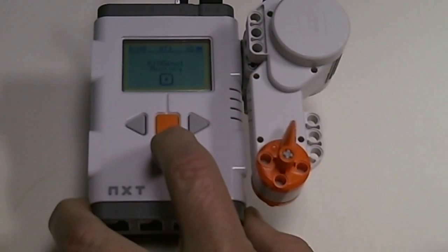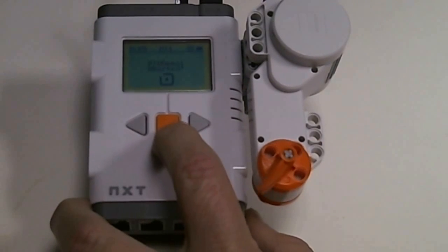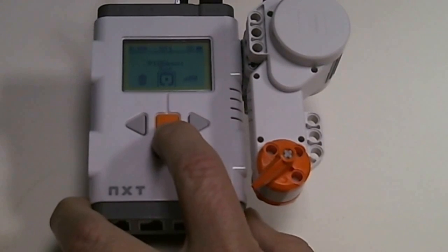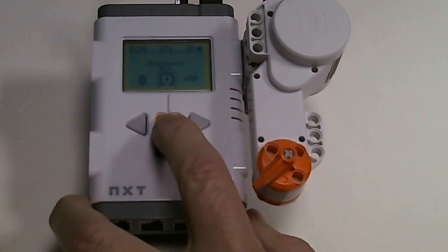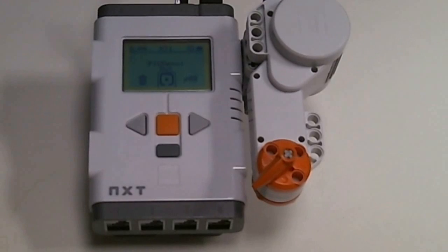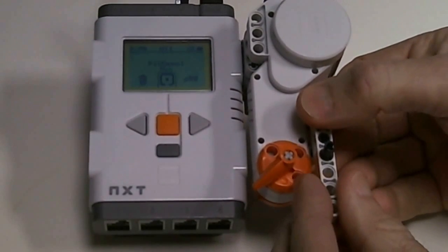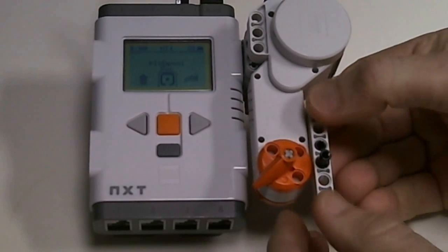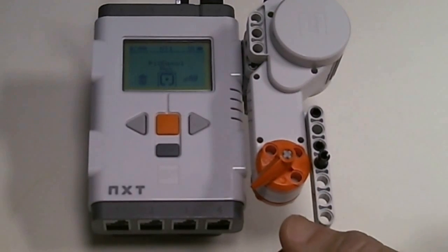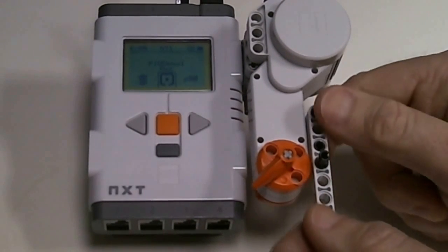If you're having a wheel on a robot that moves, then you probably don't care exactly about the position of the wheel. But if you have something like a robotic arm or a gripper or a selector, then you probably care about the motor position, the exact motor position. You want an absolute position. So there are different ways of doing this, of establishing a sort of reference for the position.